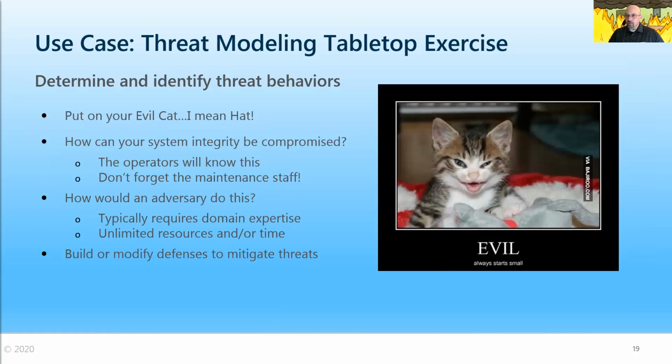They've done failure scenarios. They've done FMEAs, the failure modes and effects analysis. They've done a lot of work on how the system can fail and how those things can be prevented. But sometimes you fall into the trap of, this is your system and you know it really well, so why would somebody do a particular action? And it doesn't even have to be malicious intent. It could just be an accident. Somebody screwed up, accidentally clicked this button or forgot to do that. There are all kinds of different ways that could happen.